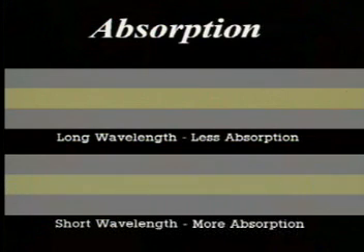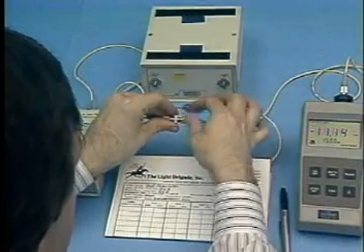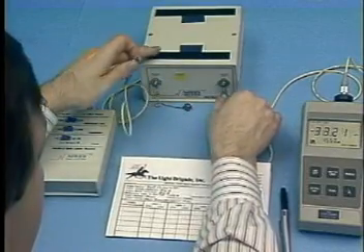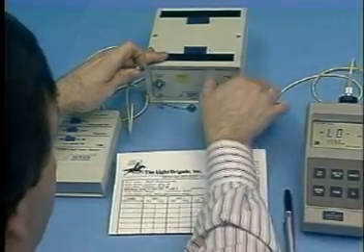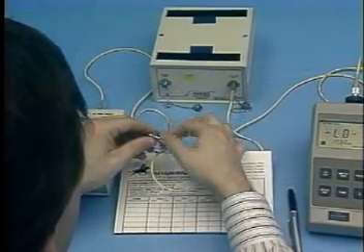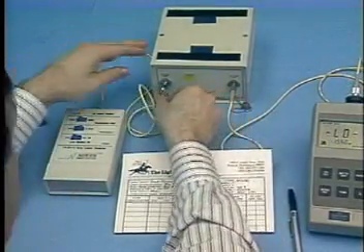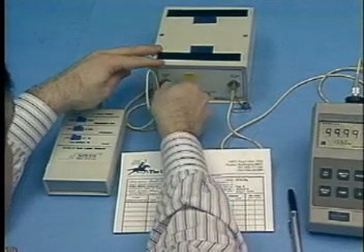The use of infrared wavelengths dramatically minimizes this effect. This is why a majority of fiber optics used in signal transmission have been designed for infrared wavelengths. The most common wavelengths used are 850, 1300, and 1550 nanometers. These wavelengths were chosen for the best performance with light sources, optical fiber, and optical detectors.